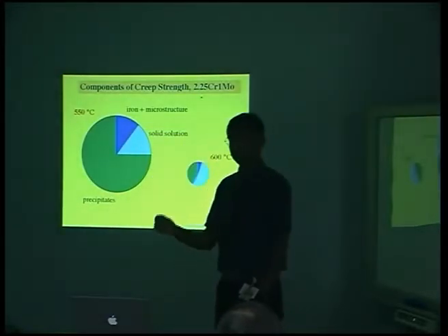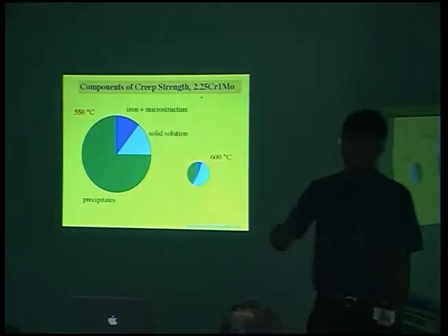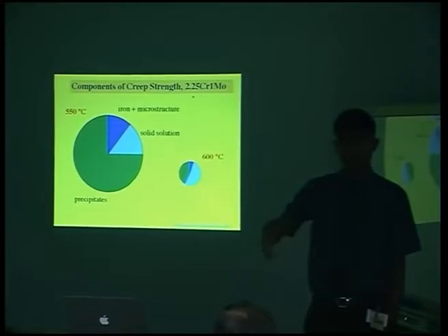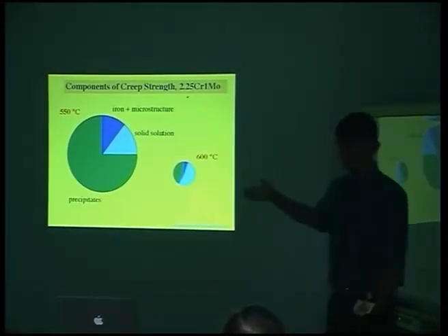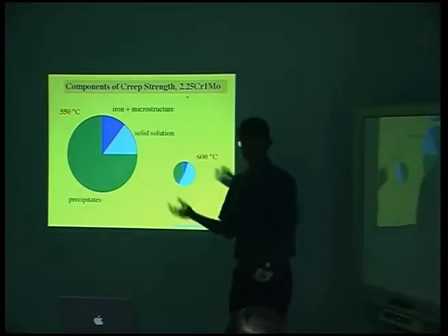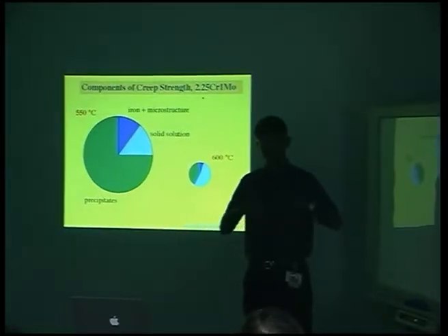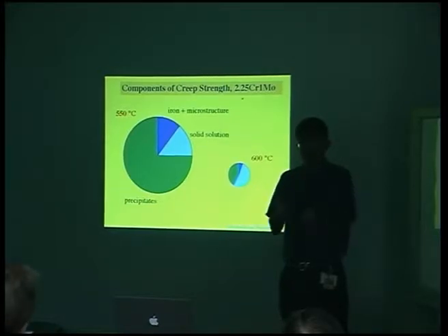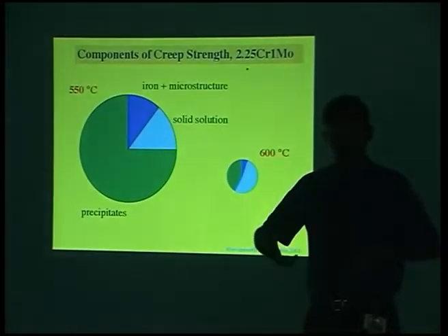You can make this very physical as well, because the inputs that you choose can be microstructure, the fractions of different carbides, etc. And then this slide which I showed you yesterday comes from a neural network model in which we are including the strengthening components due to solid solution, the carbides, etc., etc. So we can get a non-linear factorization of the strength.